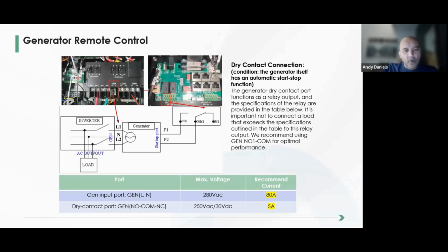It's very, very important for you guys at Charge Solar, who assist clients with setting up, as well as the installers that do this, to make sure that when you use the generator port with the generator plugged into it, that you do not inadvertently set it to smart load function, because it'll put power out on there, and we all know what happens when you do something like that. It'll damage the generator. A puff of smoke will come out of it, and not out of the exhaust, in another area, and it's very difficult to get that smoke back in again.